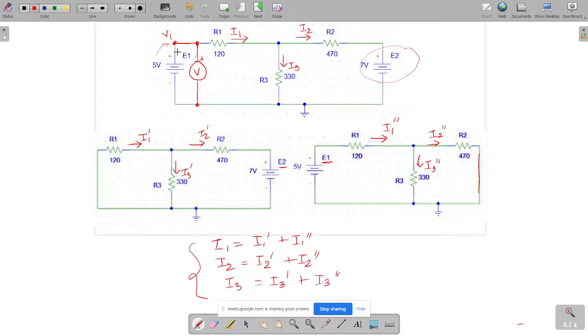Okay, so what does it mean? It means that we are finding out the voltage value of this V1, which will basically show the voltage of E1, right? Okay, so for solving the V1 voltage, we will be placing our voltmeter over here. Now if this is V2, where do we place our multimeter? Can anyone tell me where we place it?